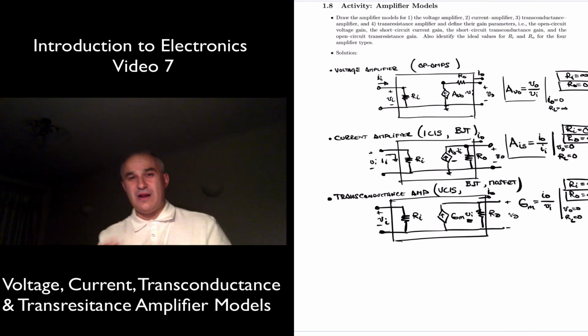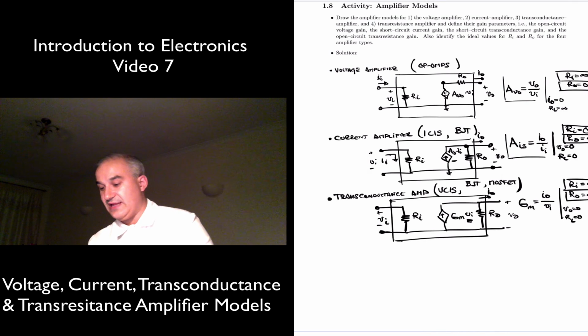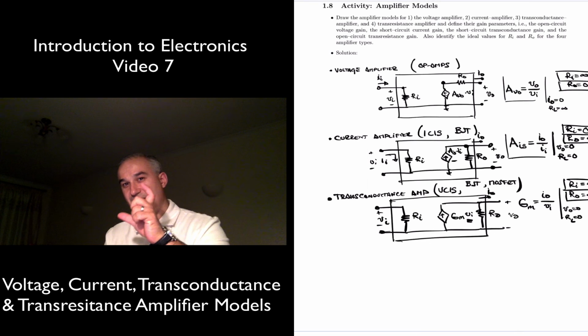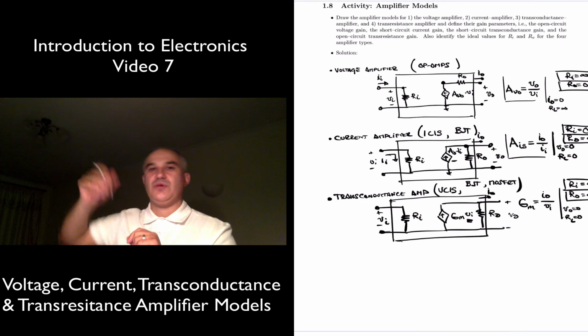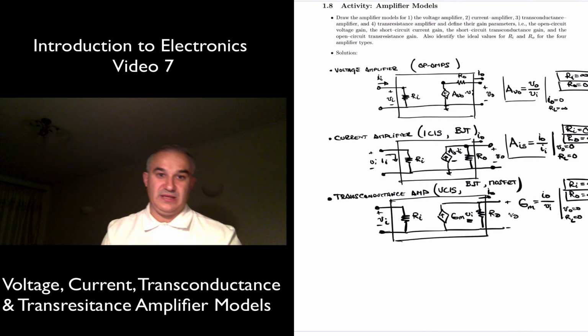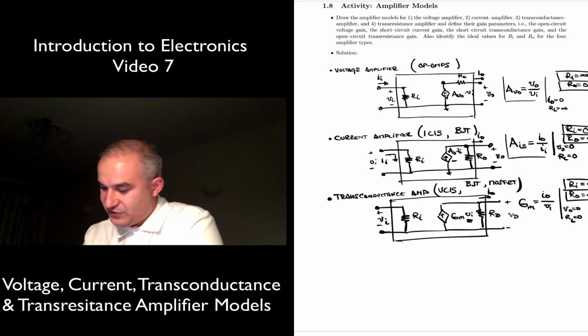So if you want a general model for all types of transistors, the transconductance amplifier works for that, where you can say, as a function of a voltage between two terminals, I get a current somewhere else. The voltage between the base and the emitter produces a current in the collector in the BJT. Or similarly, you can have it in the MOSFET with the MOSFET terminals.